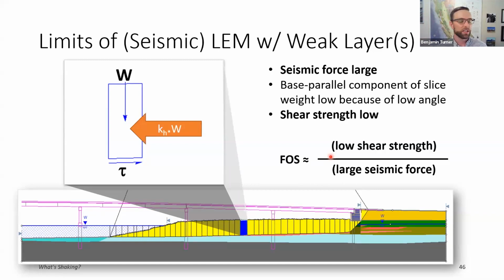And the shear strength is changing with time, especially if we're talking about liquefaction. That doesn't just flip on like a switch. It develops during the earthquake record. And even once we're in a liquefied state, it's not necessarily constant. We can get dilation spikes where things stiffen up again and all these things. So we are drastically simplifying this into 2 numbers that we represent as constants, neither of which are really constant.